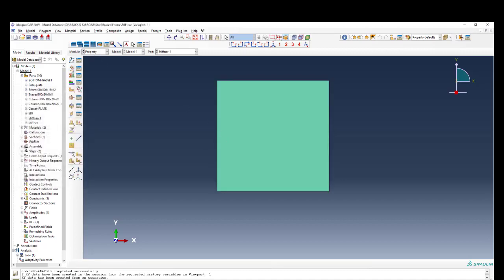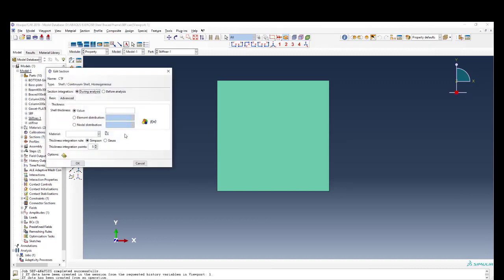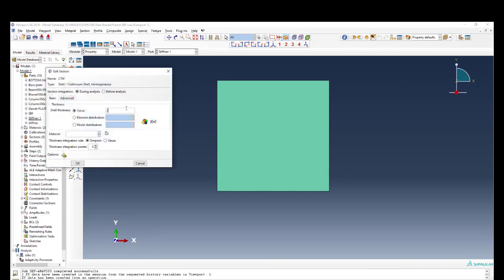Next we're going to define one called column TF. Column TF means thickness of flange. The thickness of flange is 20 millimeters, with steel 1. And one more, called column TW, with thickness of web, which is the same, 20 millimeters.